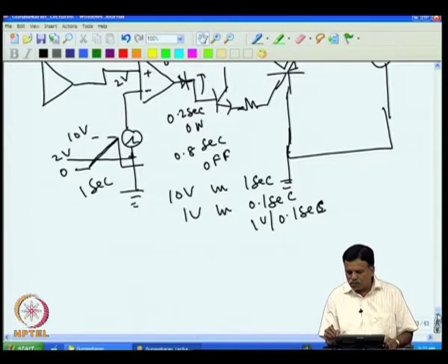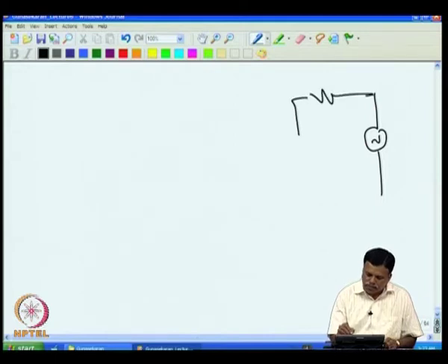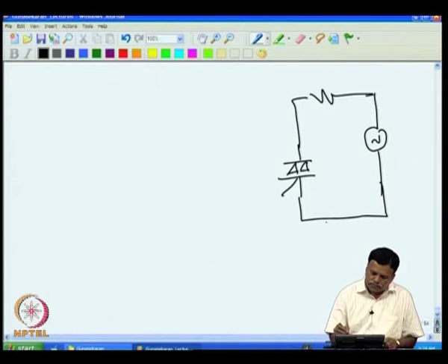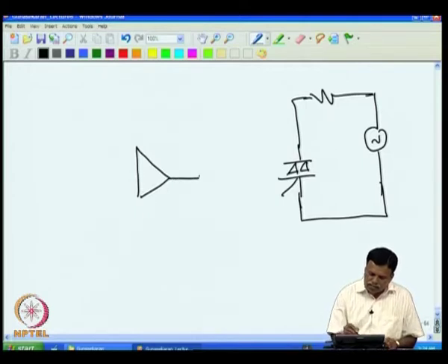If you want to break this, we can add an opto isolator to this circuit so that there is no shock hazard. So, the same thing can be modified like this. I can have an AC voltage here, and then you can have the triac, and then we can have the output from the PWM stage, that drive stage.